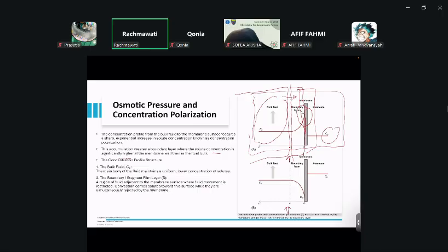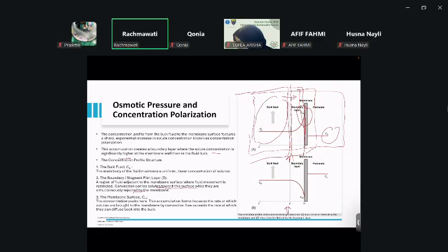This is a region of fluid adjacent to the membrane surface where the fluid movement is restricted. In this case, the convection carries solutes toward the surface while they are simultaneously rejected by the membrane. So you have an accumulation of concentration. At the membrane surface, the CM, the concentration peaks; that should be the highest concentration present in the system.